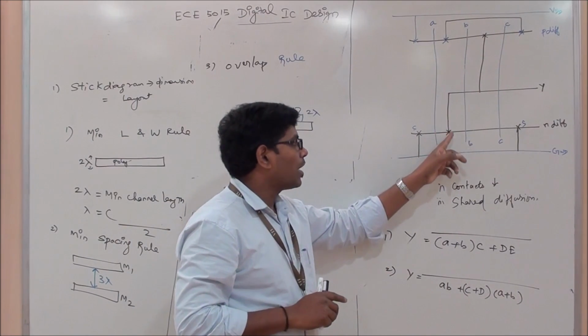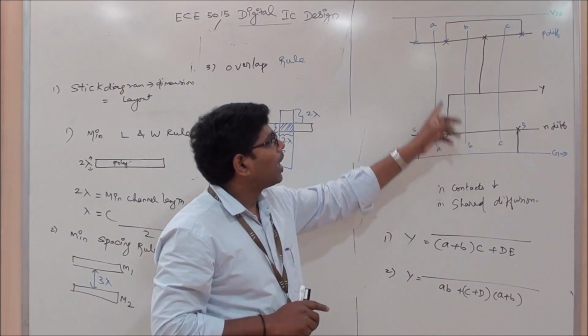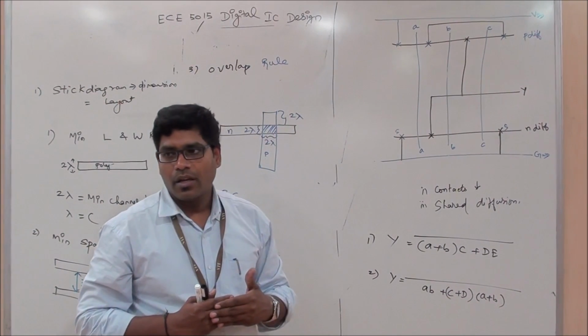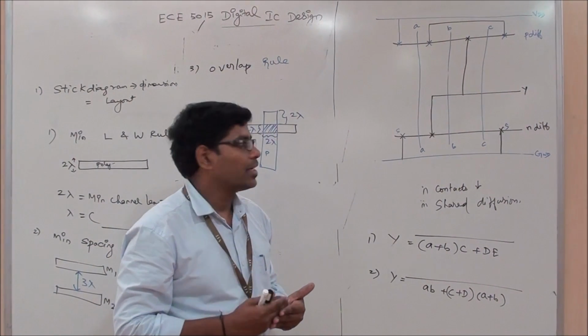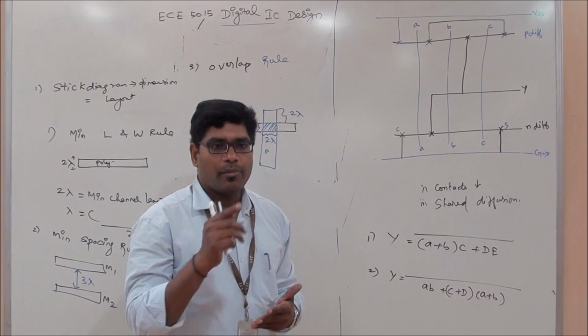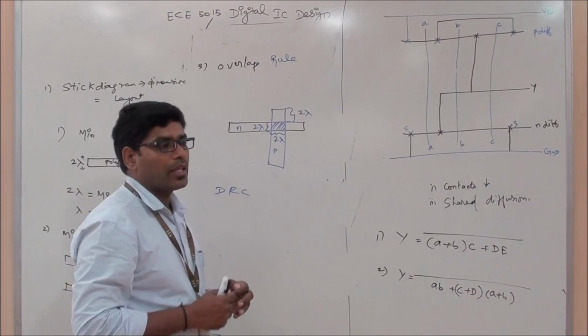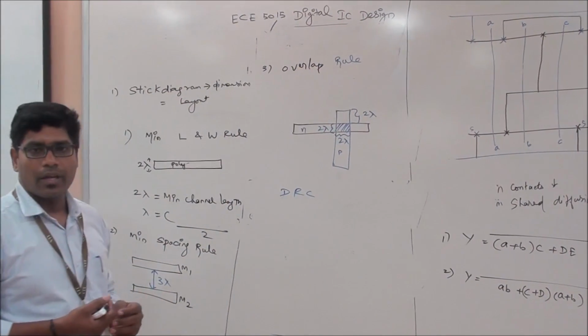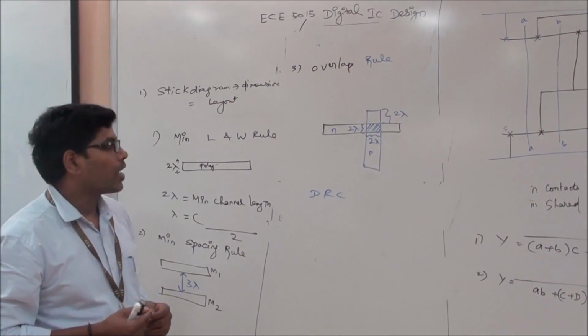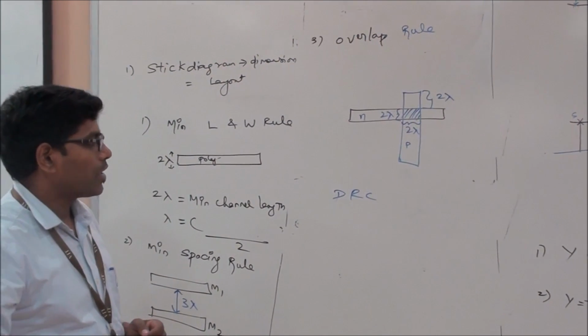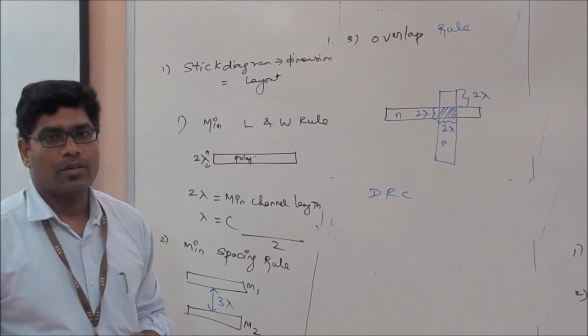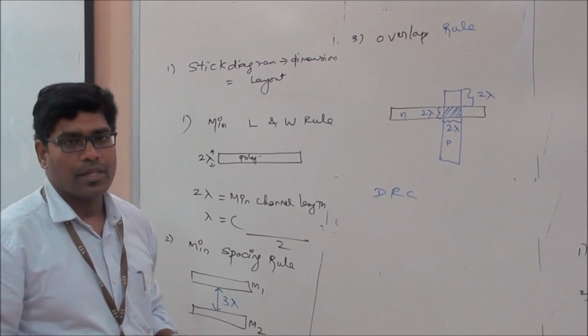This contact is a metal and diffusion contact. Like this, at different places, you will have contacts and layers, with their appropriate dimensions. You may cross-refer to the minimum rules stated by the technology file, draw the layout and cross-check for DRC. This will lead to an efficient back-end designer.